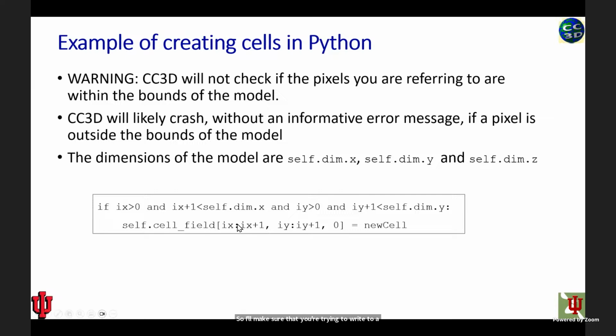So this gives you a way of, anytime you want, you can change any pixel in your model to anything else you want it to be. You can assign it to a new cell. You can set it to be a pixel of medium. You can create a new cell, put all the pixels you want into that new cell. Cells don't have to be contiguous. You can make one cell that has a bunch of pixels on one side of the model and a bunch of pixels on the other side of the model. CompuCell is not a big fan of having those fragmented cells, and it's liable to delete one of them and make the other one grow bigger. So normally you want to do contiguous regions.